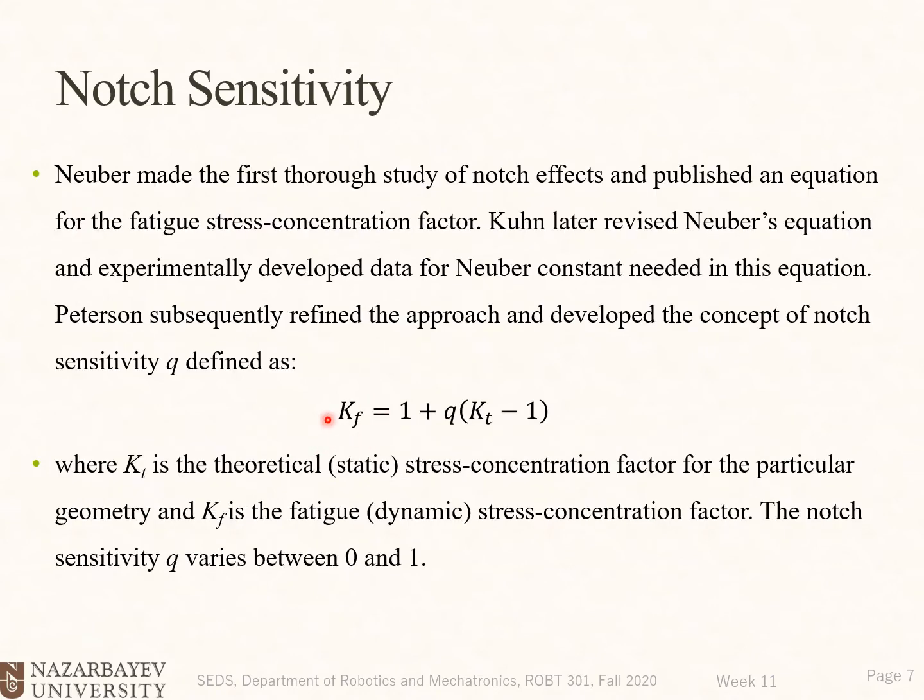Okay, so here we are going to calculate the fatigue stress concentration factor, or KF. And you see in the formula we have KT, which is the geometrical stress concentration factor, and we have Q, and Q is the notch sensitivity factor. Neuber is the name of a scientist who made the first true study of notch effects and published an equation for the fatigue stress concentration factor.